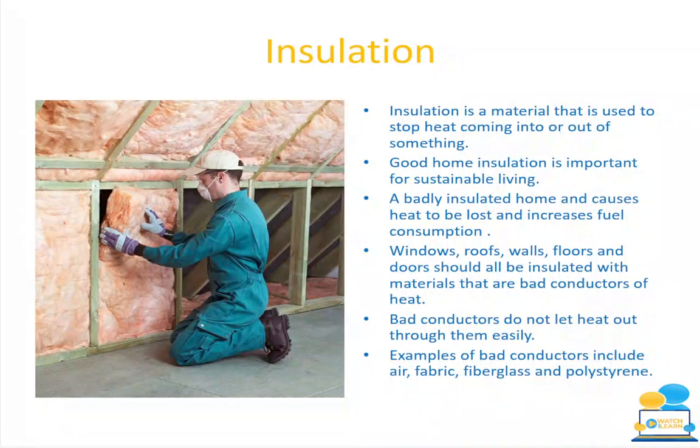If a home is really cold, it more than likely means it is badly insulated, which means that you're going to have the heating on a lot more, which therefore means you are increasing your fuel costs, which means you're not living sustainably. Your windows, your walls, your roofs, your floors and doors should all be insulated with materials that are bad conductors of heat, okay? Otherwise you're going to have the heating on the whole time.